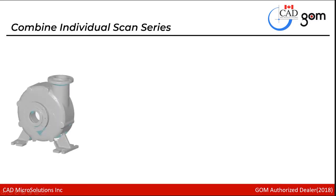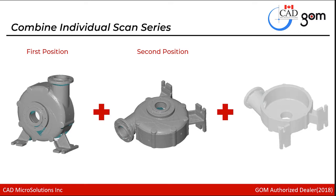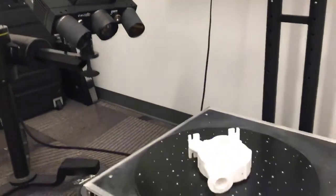So now that we've completed scanning the object in its first position, we now need to reorient the part on the table into its second and third positions to capture the remaining geometry. So once we've done this, we will combine all 3 individual scan series into a single uniform mesh.